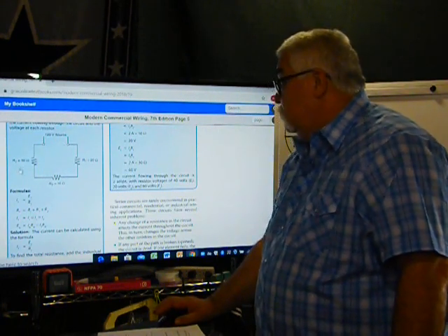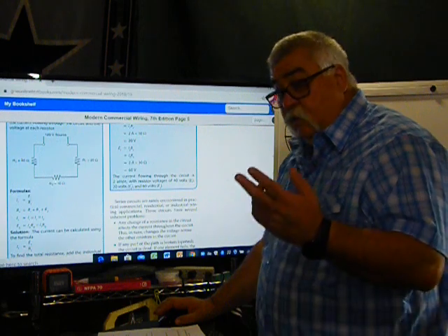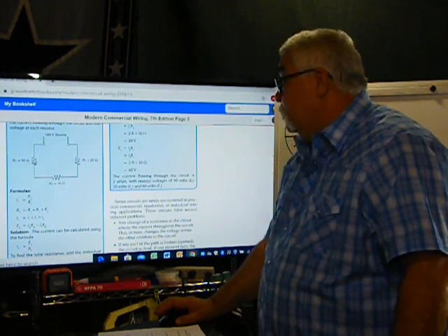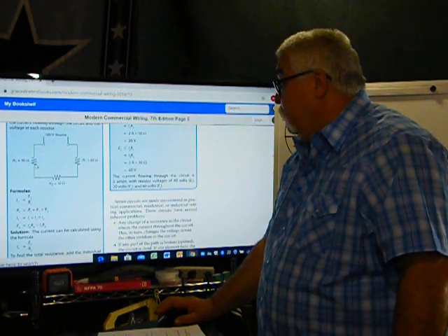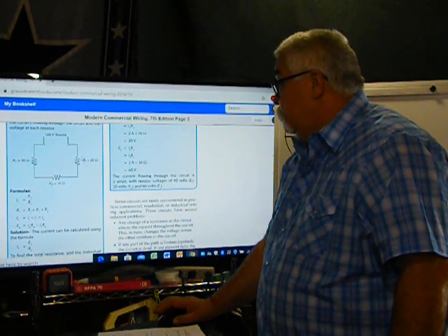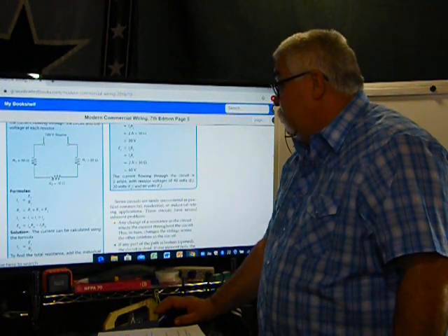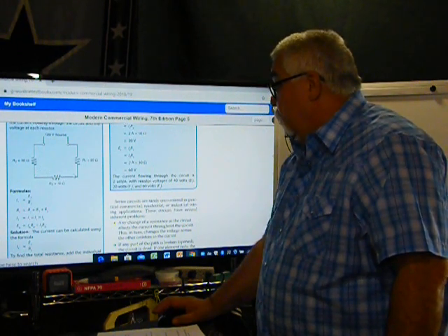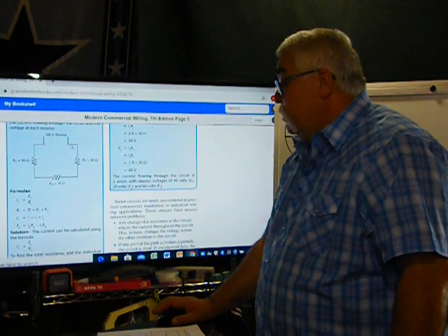So the voltage drop equals the total current times the resistance. Here, this was 60 volts, this was 20 volts, and this is 40 volts. So 60 volts leaves me 60 volts, 20 drops here, that leaves me 40, 40 goes across here, and it gives me back 0.